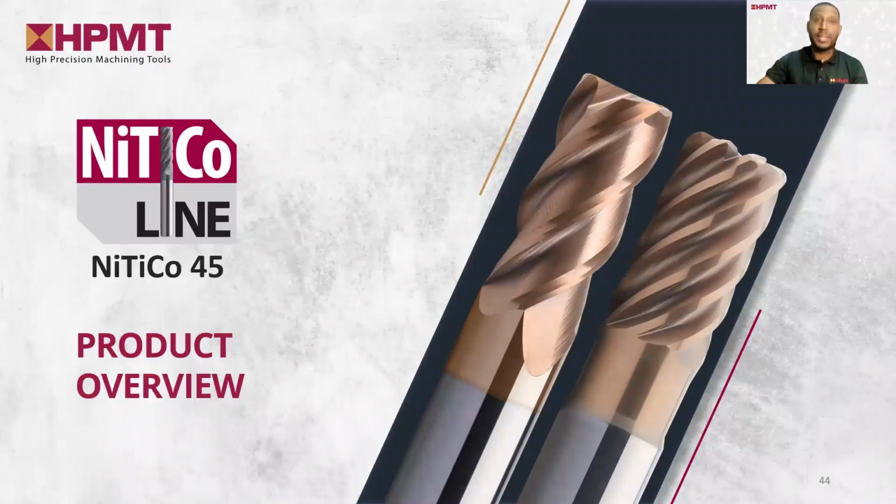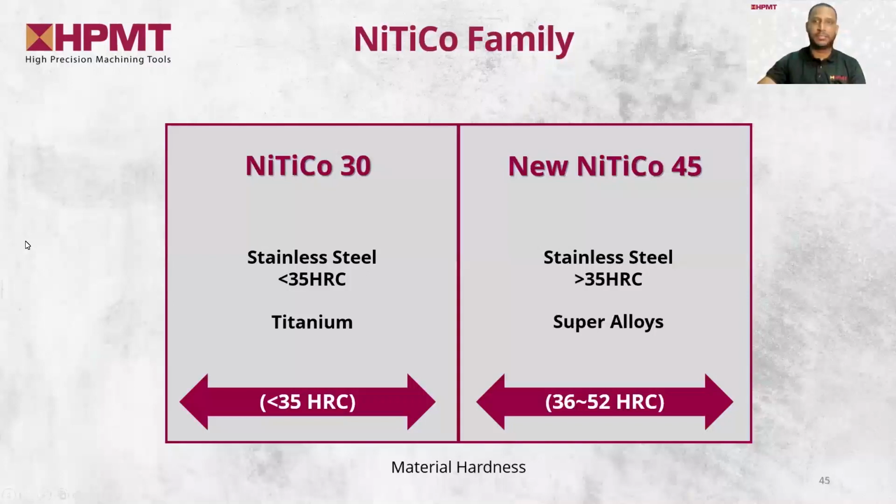Okay, I'll pass over to my colleague Nisha to share on the product overview series. Thanks, Mark. HPMT has 2 product lines which are well known as NiTiCo30 and NiTiCo45. In today's webinar, we'll be focusing on the NiTiCo45. You can further engage with our sales team if you're curious about NiTiCo30, which covers the lower range below 35 HRC. Our existing NiTiCo45 has a cutting range from 36 to 52 HRC.